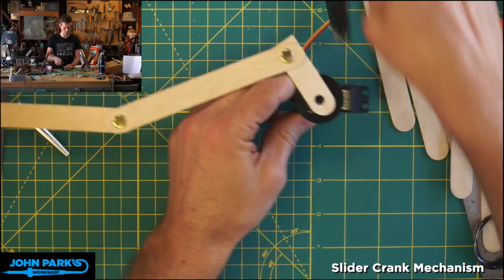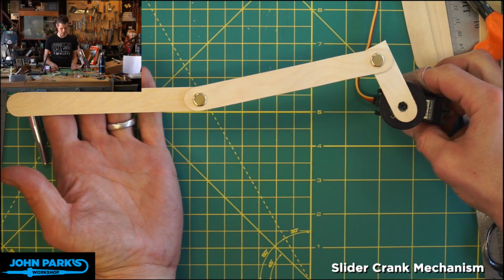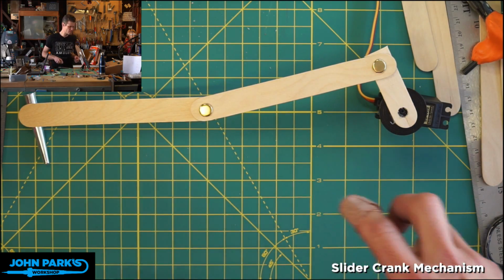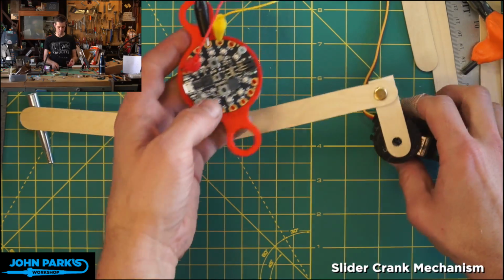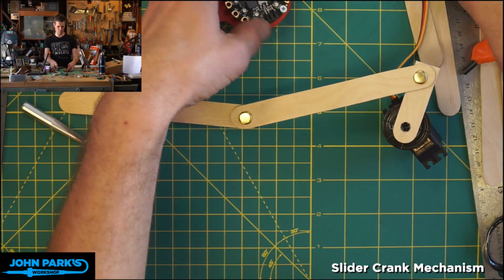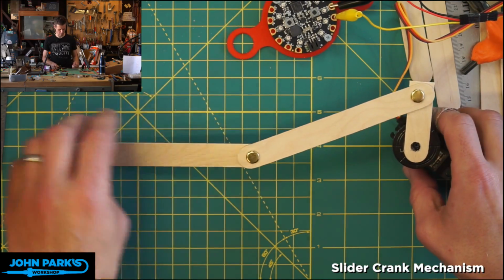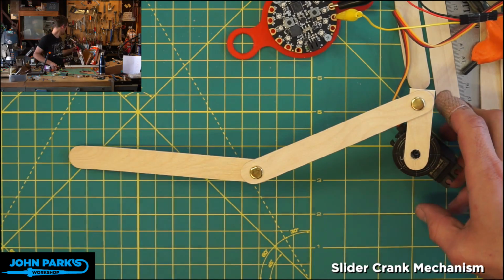And so why don't we actually hook this up just in free space and we can see it in its auto action mode. One thing I found is that I think we're potentially stalling out this little motor when we draw a little too much current over a USB connection when it's just connected to the computer. So it's either good to use a battery or a plugged-in USB connection. So we won't need our hot glue anymore.